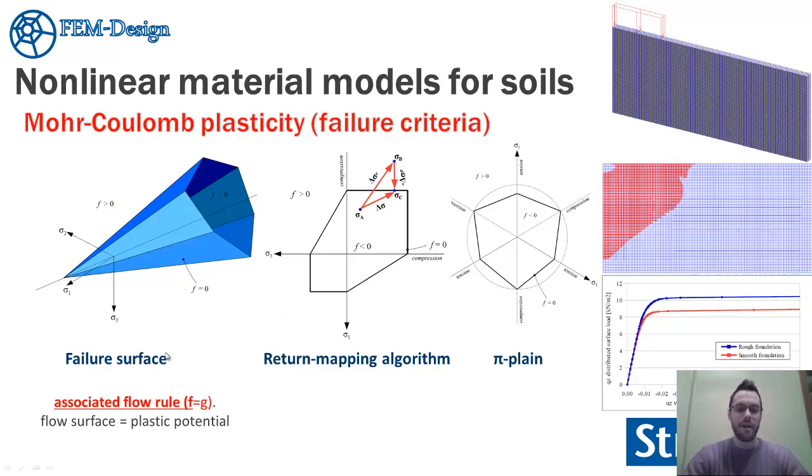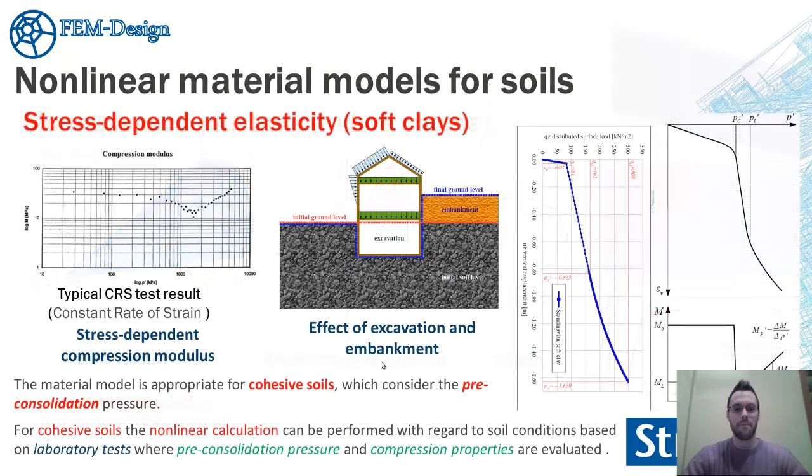So in FEM-Design we are considering an associated flow rule. So the plastic potential and the flow surface are the same function in FEM-Design. In this case, the material stiffness matrix, and based on this material stiffness matrix, the global stiffness matrix will be symmetric also in FEM-Design.